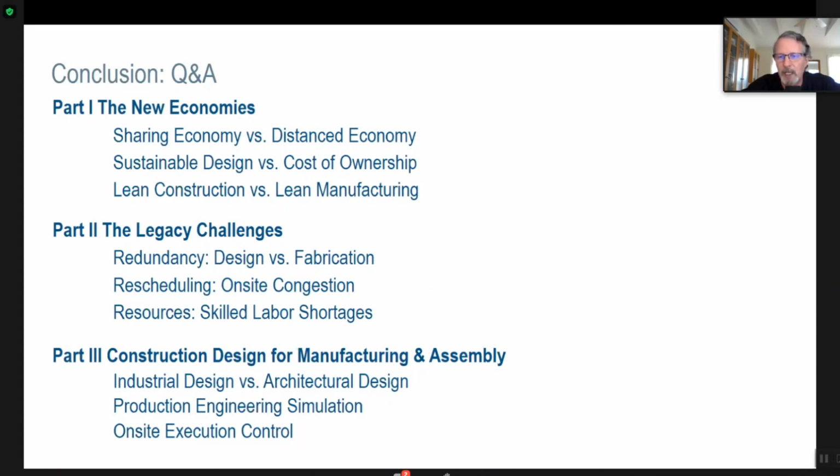Concrete, I think, is a bit of a laggard, but for some reason in many parts of the world, most of the offsite and manufacture is a concrete type process. I see more promise with GFRC, or glass fiber reinforced concrete. Those systems are lighter weight, better performing, and have less carbon problems, I guess, than traditional concrete. So I think we have to look at hybrid systems, and I think that a focus on just one system